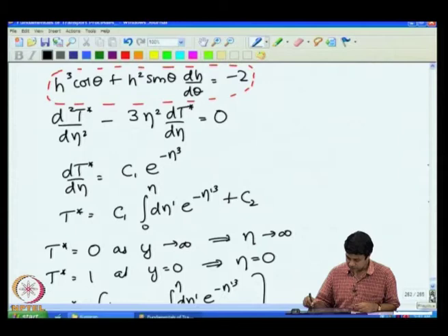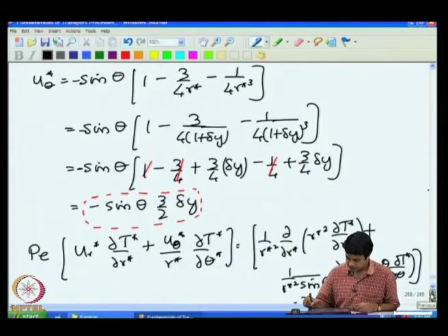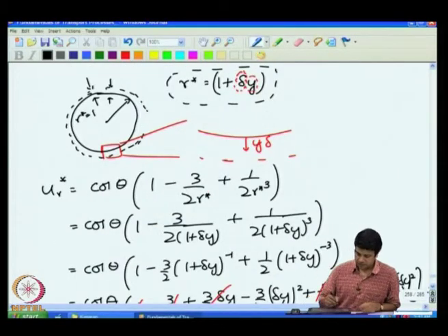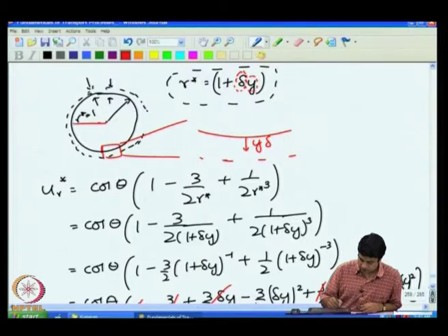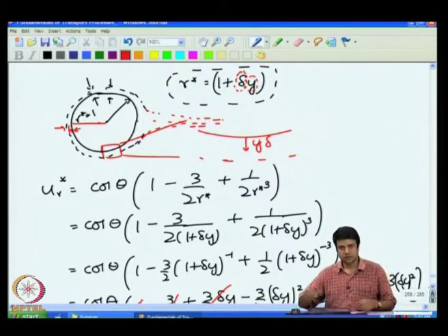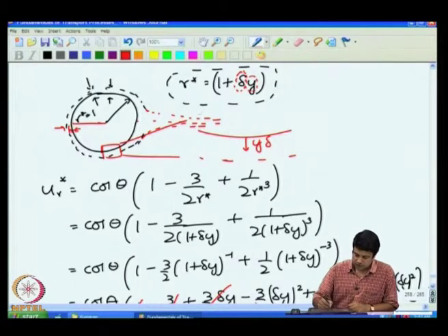What that means physically is that there is a boundary layer around the sphere, but the part that I did not continue for you here. This is the upstream side. Here you have some finite value of h on the upstream side. However, on the downstream side h actually goes to infinity. That means that the boundary layer looks something like this. The value of h actually goes to infinity as you go downstream. This region here is what is called the wake.